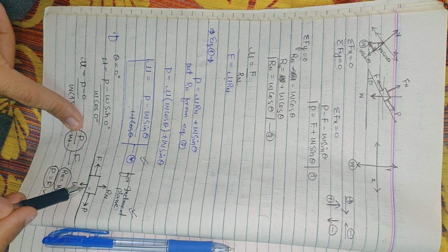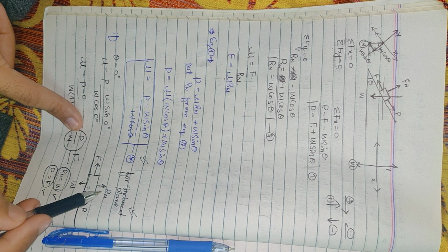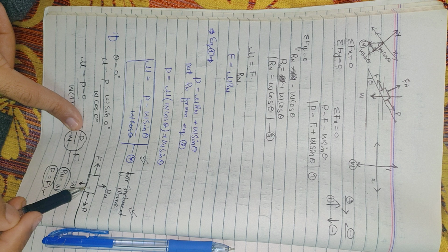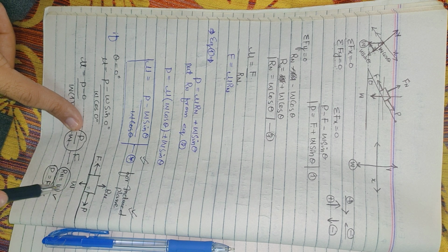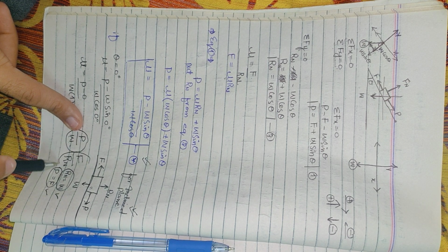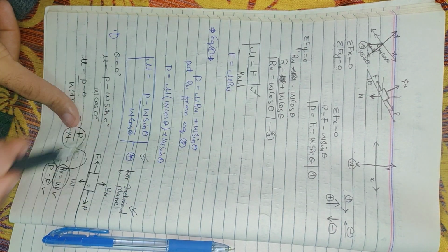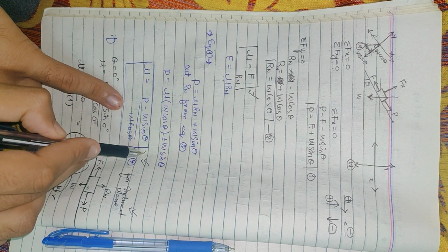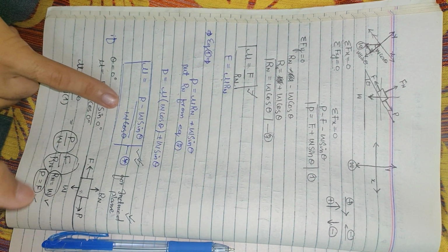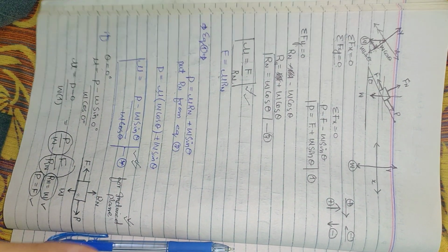We saw that the weight is equal to the normal force, so for W we can write Rn, so mu is F divided by Rn. This makes this equation. When there is an inclined plane, we can use the earlier equation. When there is no inclined plane, we can use this simple equation. So this equation is used to find the coefficient of friction.